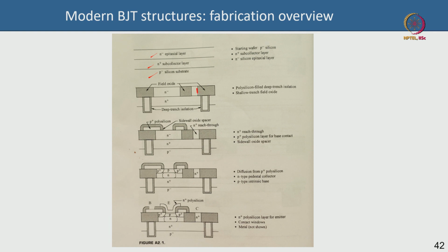So, you will etch and form this deep trench isolation here. This is basically filled oxide, SiO2, and this is polysilicon wrapped around it, the deep oxide that makes it deep trench isolation that separates devices. Okay. Then after that you make an ion implantation, for instance, or maybe diffusion in earlier days, to make an N plus sinker region, or a reach-through. This is your N plus sinker region.